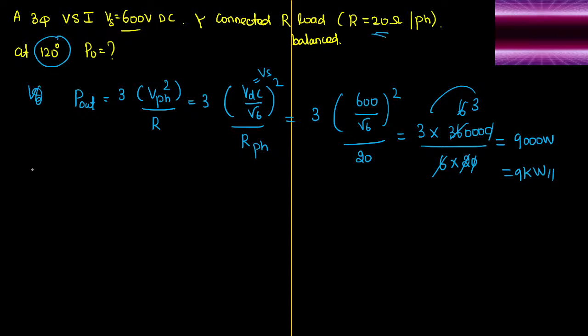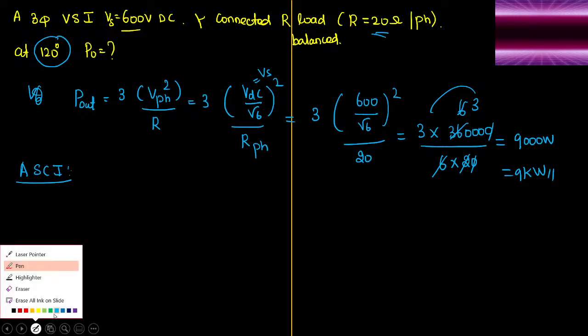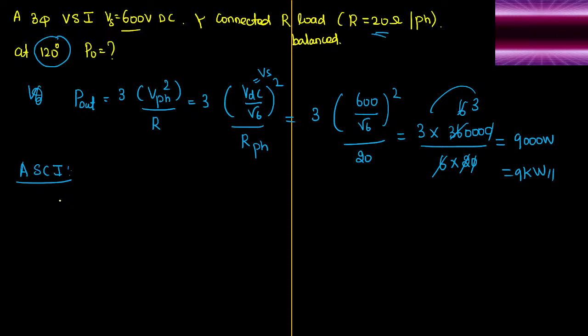There is one more inverter called the auto sequential commutated inverter. Do you remember? If you observe the auto sequential commutated inverter, the question often asked is to calculate the value of minimum circuit turn-off time. The minimum time taken by the circuit will be 4 times RC.